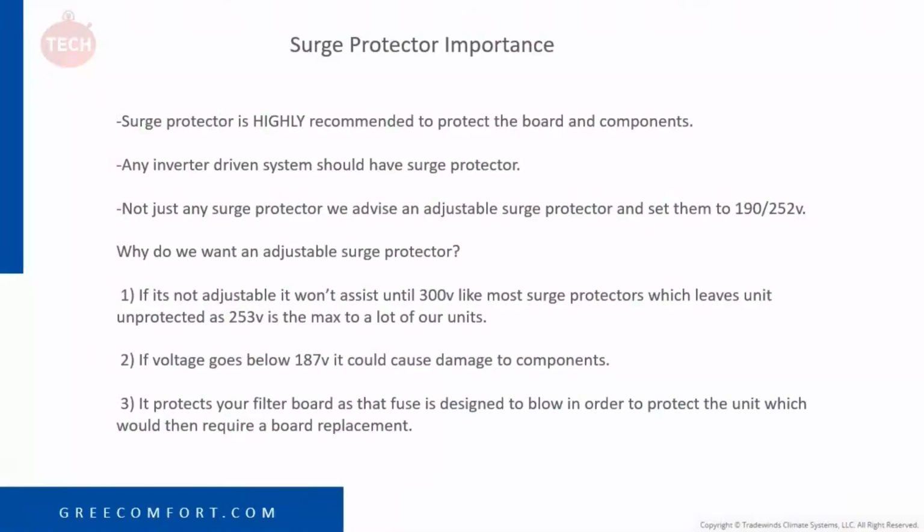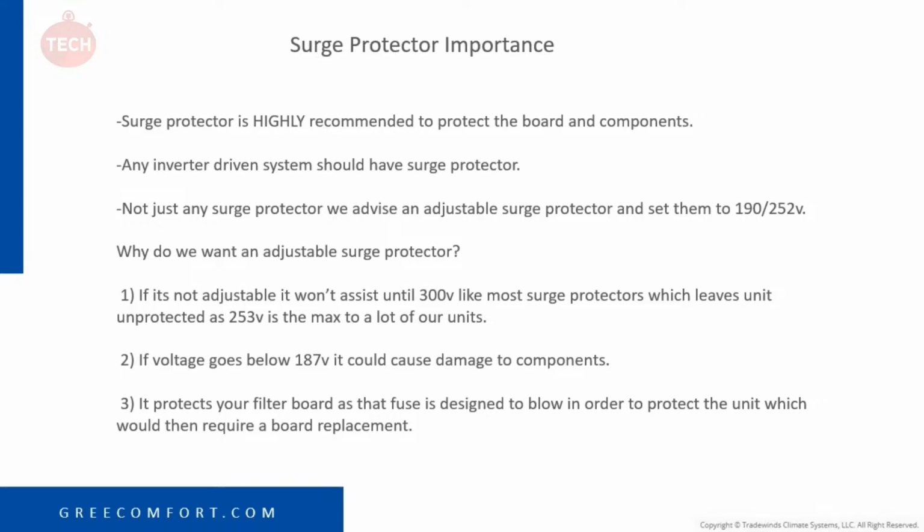Ideally, you want to have an adjustable surge protector. If you do not have an adjustable one, it won't assist until 300 volts, like most surge protectors, which leaves the unit unprotected, as 253 volts is the max for a lot of our units. And also, having an adjustable one, you can set it. I always recommend setting it for 190 and 252. Again, because if it goes below 187 volts, that's the lowest input voltage the unit can have. That could cause damage to the components as well. So again, an adjustable surge protector is recommended.